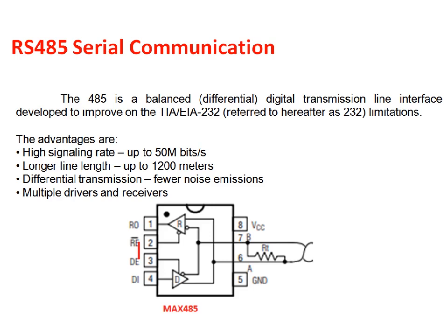Because it uses a differential signal, it is less susceptible to noise, and it supports multiple drivers and receivers, whereas RS232 supports only one driver and one receiver. The most commonly used IC for converting the TTL serial data to RS485 logic levels is MAX485. MAX485 supports half duplex.